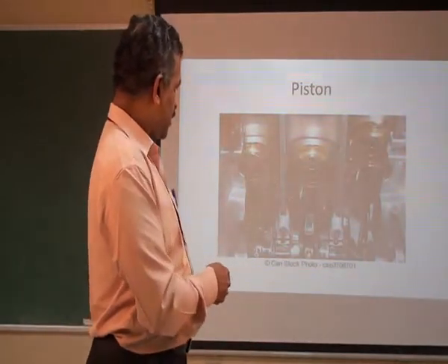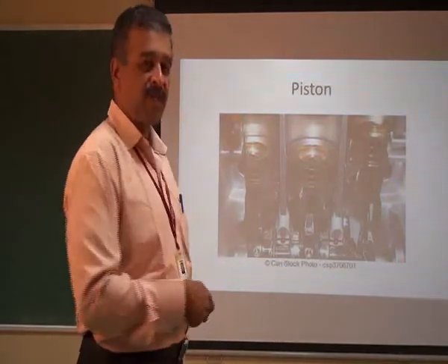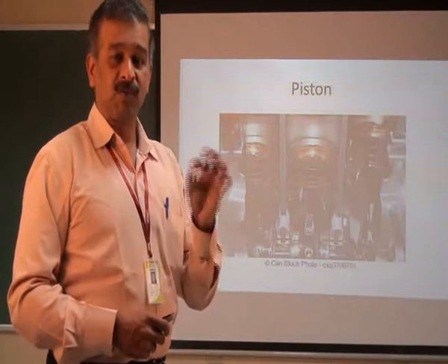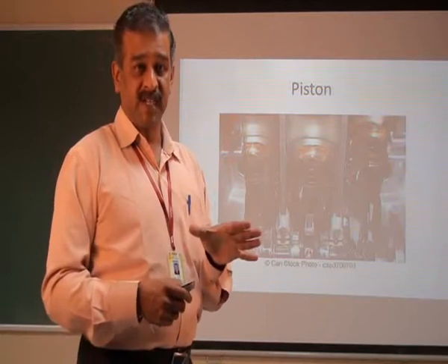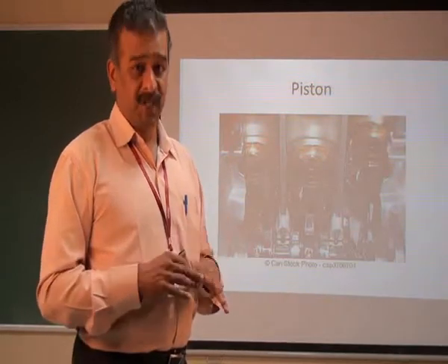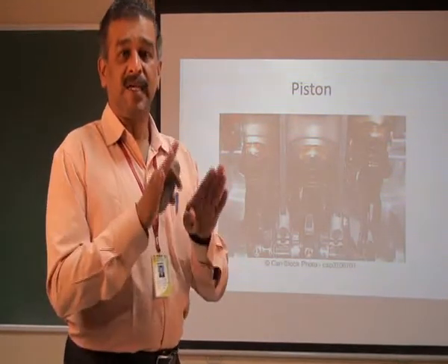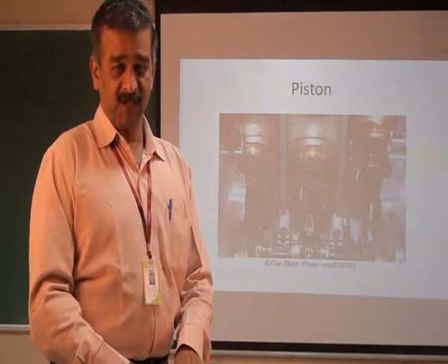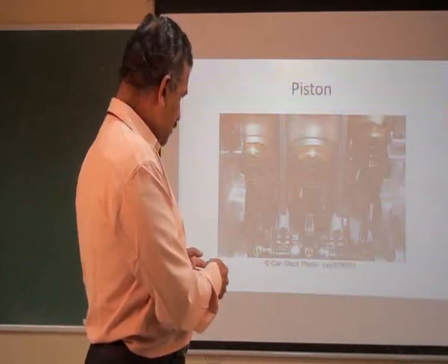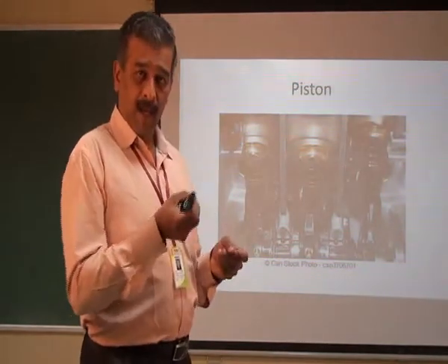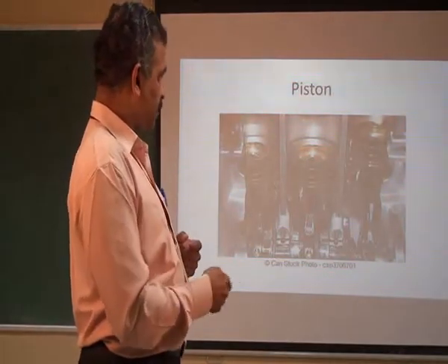I told about the piston, and you can see some grooves, 1, 2, 3. They are called grooves. The provision for the grooves are piston rings. We have to provide piston rings to avoid the escaping of the burned out fuel. The burned out fuel should push only the piston downwards. It should not escape through anything else. So that is the main purpose. These are the grooves provided for rings, and you can see the connecting rod. This is the crankshaft. This is the complete about the piston.